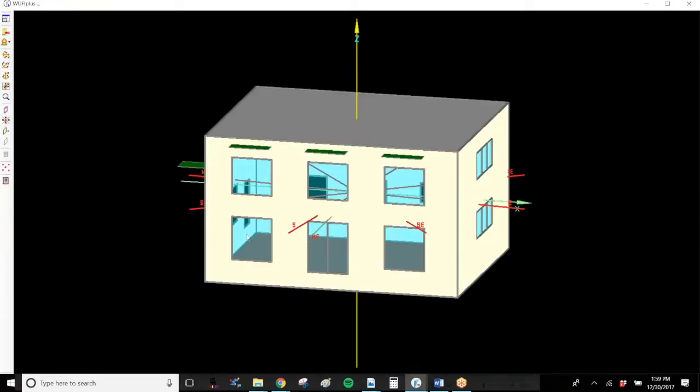In my geometry screen, the first step I will take is selecting vertices here. On the left hand side, it looks like a little 5 on the dice, and this now makes the red vertices appear in my geometry. I'm doing this so that I can create new vertices relative to the old vertices. That's how most of the new geometry creation will work in WUFI Passive.